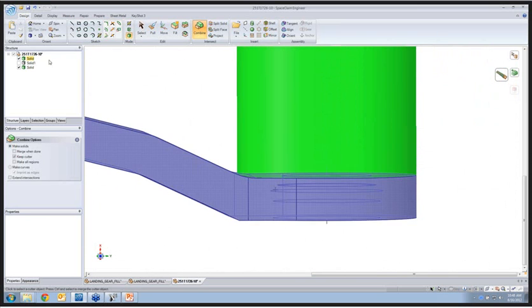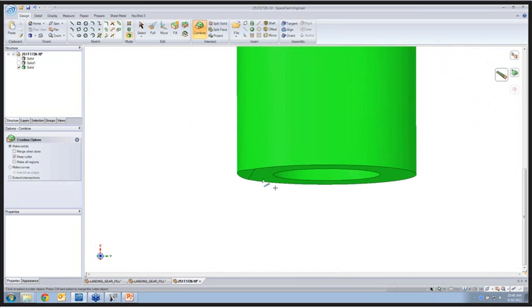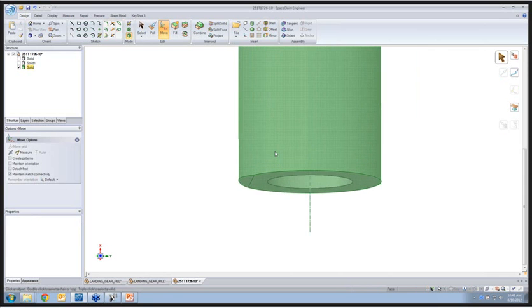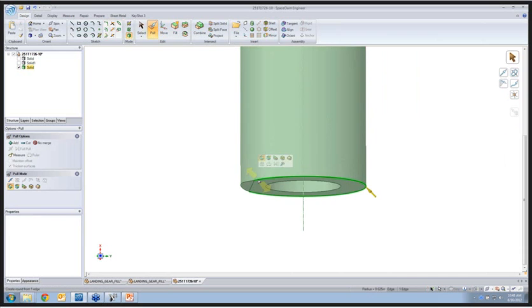Okay, so going back into a 3D mode, maybe I want a little bit of clearance between that small lip and the workpiece, so I could elect just to move that radius. That's actually a cylinder. Just move it a little bit, maybe 10 thousandths or 20 thousandths, to make a little clearance, and I'm good to go. From here, maybe you decide to put some rounds on the edges. I can do that. SpaceClaim, no problem. It's all done with the pull tool.